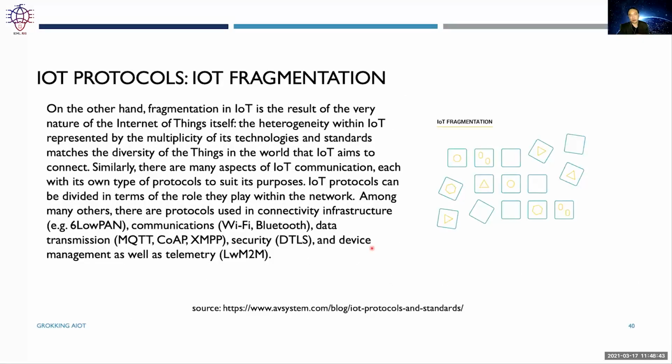So we can see that in the IoT space there are different radio technologies, and they have an underlying reason for it, which is the very wide range of use cases, right? We can't be transmitting very fast, over long distance, and at low power at the same time. So something has to give. For different radio technologies, they focus on different things.